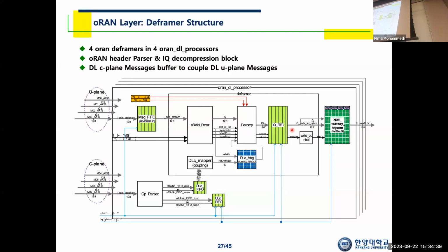Then you decode the header, then you find, oh, this has been addressed to me, okay. Then you are left with the eCPRI packet, then you decode the eCPRI header to find whether you have received a uPlane message or cPlane message. Okay, oh, this is a cPlane or uPlane message, okay, fine. Then you finally decode the ORAN header, then you know how to map this payload back to the original OFDM sample position.